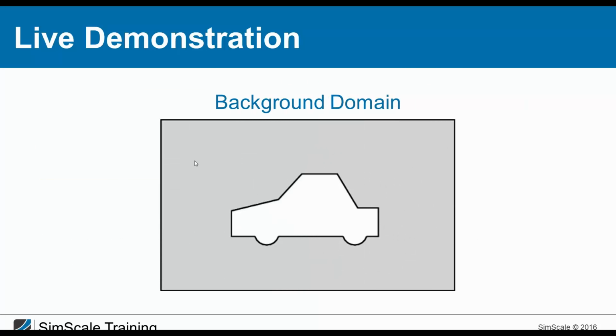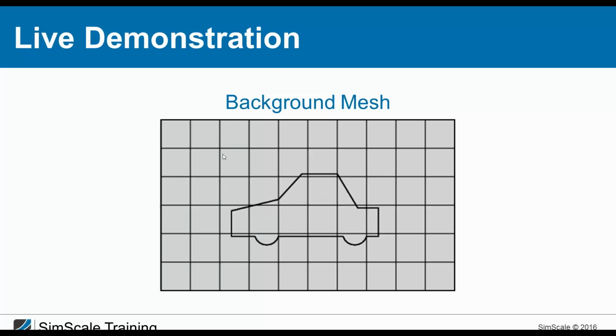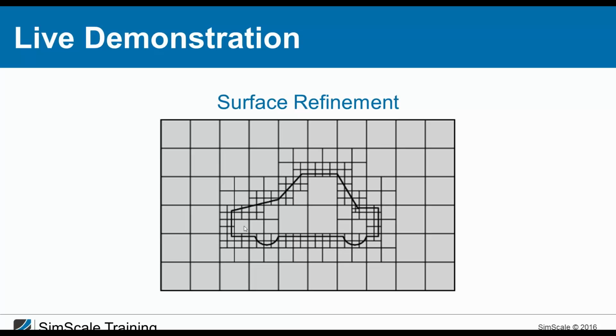As you know, our aim is to create a mesh around this car geometry. So we need a mesh of the fluid domain around the car. In contrast to a lot of other simulation tools, where you need to invest a lot of time in preparing a CAD model, we have a very robust tool called snappyHexMesh. It is based on creating a background mesh and in the end morphing this mesh to the geometry you want. First of all, we create just a block mesh, so just a meshed block, our wind tunnel. Then the mesh is refined based on our settings near edges and around the surfaces of the geometry.